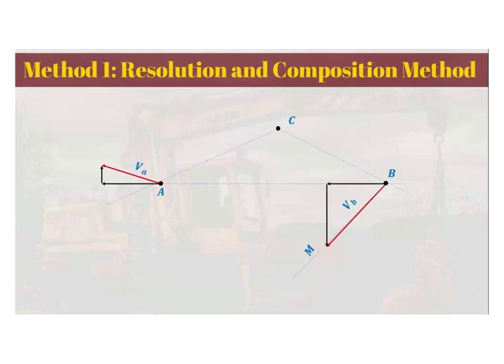Now, we wanted to find as well the absolute velocity and direction at point C. So what you're going to do is first you are going to resolve again A into components along the line joining it with C. The line joining A with C is this line here. Extending that line, so we have the line AC. We are going to resolve the velocity of A along this line. We have the horizontal and the perpendicular components. So let's start first with B. So the line joining C to B is this line here as well, as you can see in the diagram.